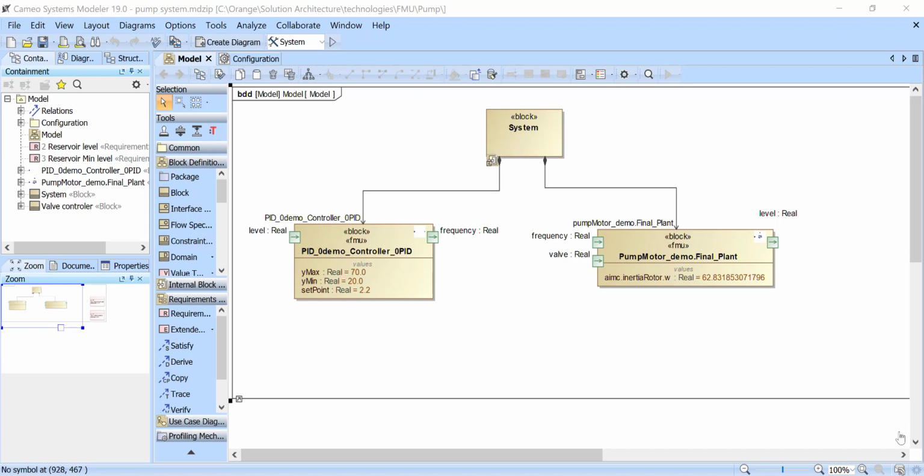So we will use FMU functional mockup units, which are based on the functional mockup interface standard, perhaps the most popular simulation tool interchange standard, supported by more than 100 tools already, which allows you to export executable models to other tools and to execute them without the original tools or with the original models. Dymola supports the standard very well.